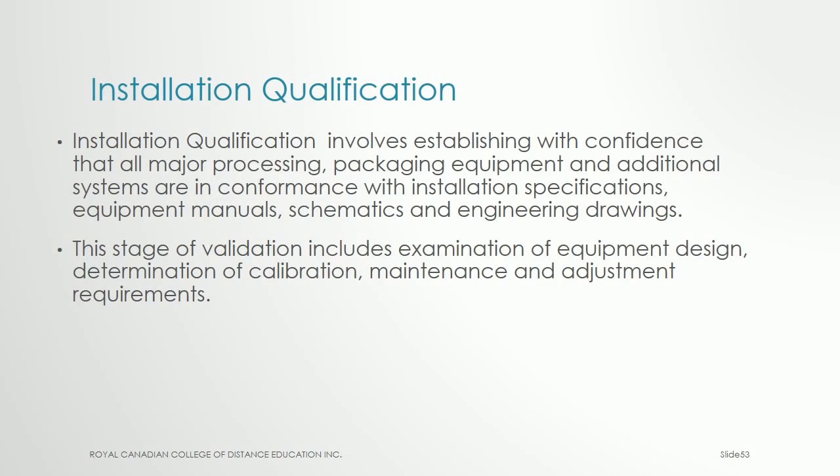Installation qualification, on the other hand, involves establishing with confidence that all major processing, packaging equipment and additional systems are in conformance with installation specifications, equipment manuals, schematics and engineering drawings. This stage of validation includes examination of equipment design, determination of calibration, maintenance and adjustment requirements.